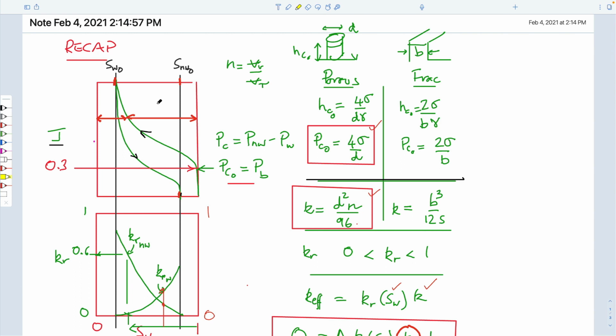We defined capillary models for them, for capillary tubes and for fractures, shown here on the right-hand side, and used that to say something about the pressure difference between the two fluids. And then we developed our understanding of capillary pressure versus saturation curves, this figure on the top left, to be able to describe exactly, for real geological media, what they would be, and identified some important locations. One is the irreducible saturation of water. You can't get any more water than that out of the system.